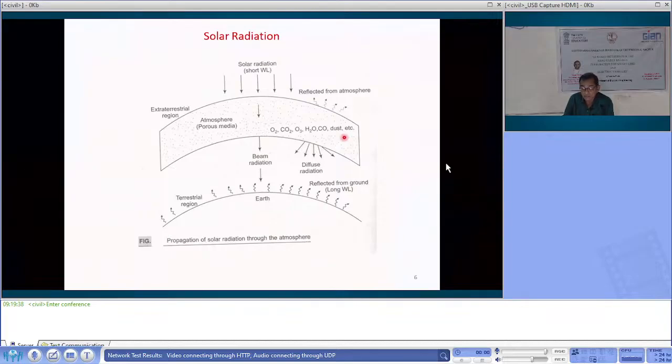Because this dust gets accumulated on the panel, that reduces the efficiency of the panel. So the only maintenance is regular cleaning. There will be bird droppings, okay. There will be shadow from a nearby building or tree. So one has to inspect the site.